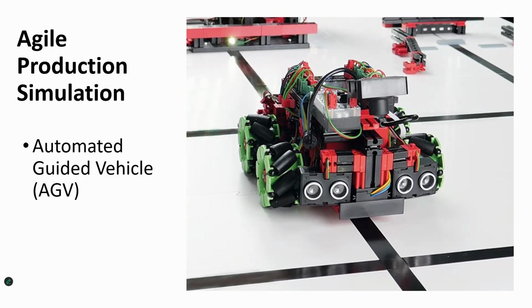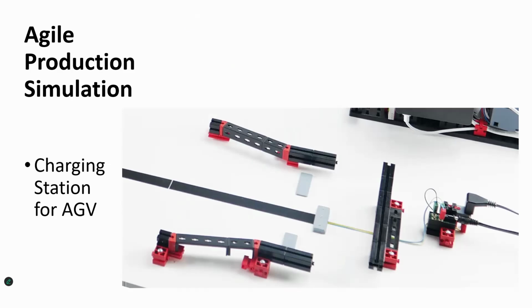Now, speaking of the battery pack, when the battery on the AGV runs low, the AGV will navigate towards a charging dock where it is automatically charged with a charger with charge monitoring. There are contacts on the bottom of the charging station that can connect with the underneath of the AGV and its charging electronics. And there you go, you get it charged up.